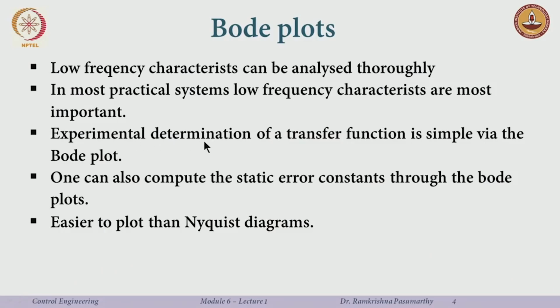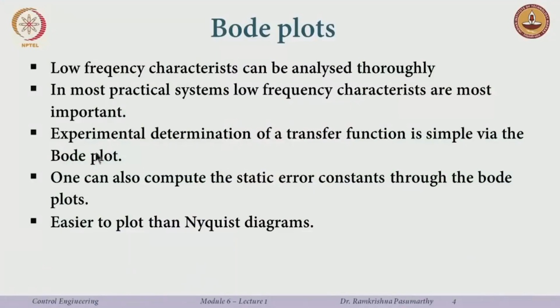Experimental determination of a transfer function is simple. If I just plot how the system gain and the phase change, in a way that I give the system lots of signals of varying frequencies, of course sinusoidal signals, and I just see what the output is. So earlier I said that I will do this experimental determination of a transfer function as part of this lecture, but I will do a slight detour.